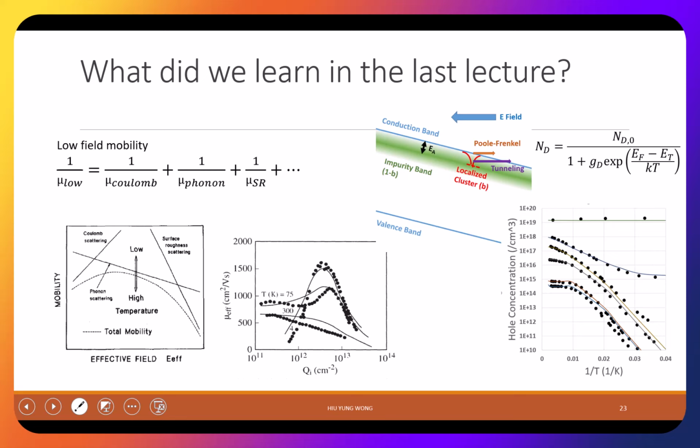Yeah. Because you are at lower temperature, you will have a lower thermal velocity. So you stay longer in the field, you get more, right? If you just zoom very fast and leave it, you only feel a very brief time, right? So that's why here Coulomb scattering is not shown here. But if you go to lower temperature, you actually have more Coulomb scattering. Means lower mobility. Okay, don't mix up scattering and mobility, okay?